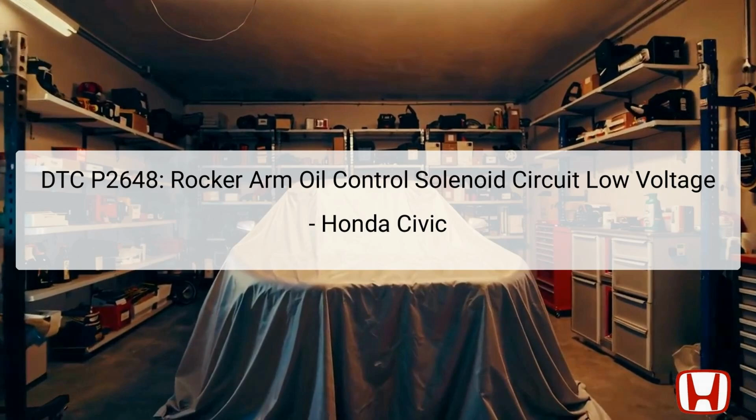DTC P2648 indicates a low voltage condition in the rocker arm oil control solenoid circuit. The rocker arm oil control solenoid plays a crucial role in the variable valve timing and lift electronic control (VTEC) system in Honda vehicles. This solenoid is responsible for regulating oil pressure to the rocker arms, ensuring that valve timing and lift operate efficiently under different driving conditions.